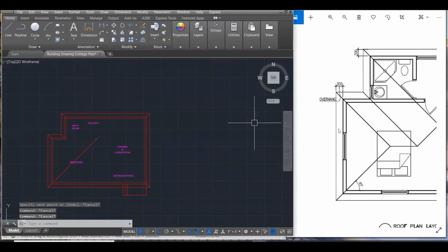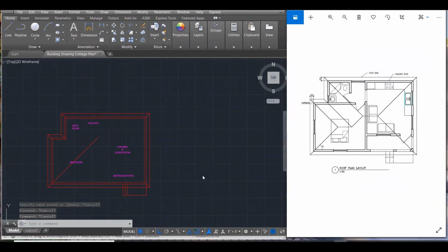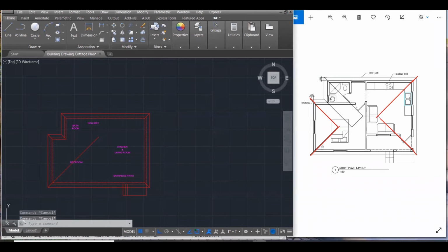And now how do I move? So let's look back at this. The first two that I'm going to be doing to show you how this works are going to be these two here. So I'm here. So say I'm here, right? And I'm here. I'm just going to fillet this by connecting that. And I'm going to take this and that and then fillet. That will go to there and that will go to there. So I'm just going to be using the fillet tool to get these to connect. And where the fillet tool can't work, I'll be using the line tool to draw. So let us proceed.